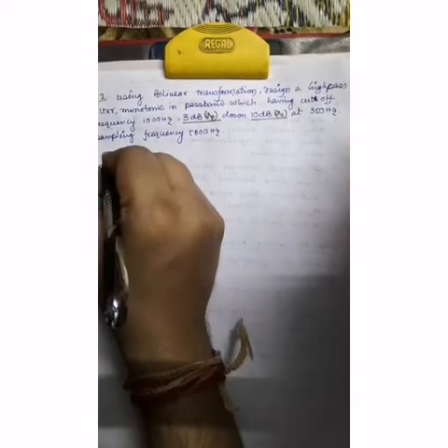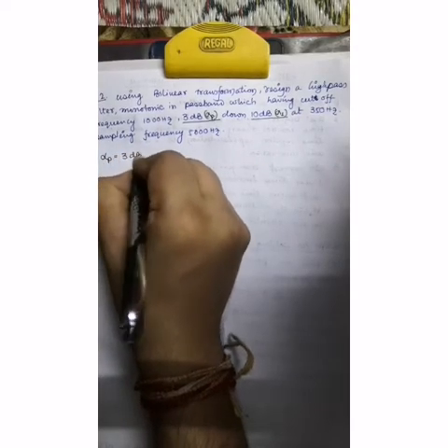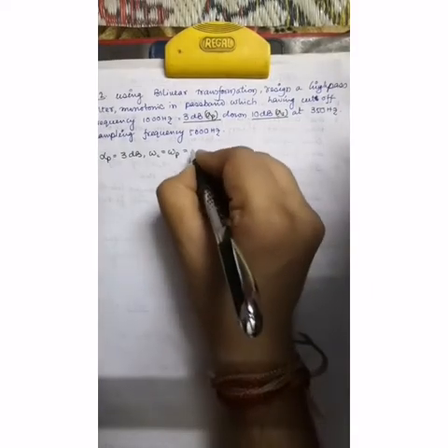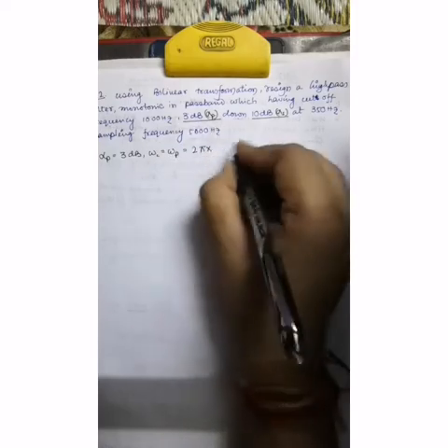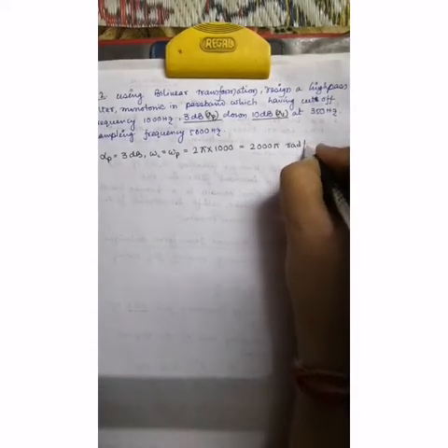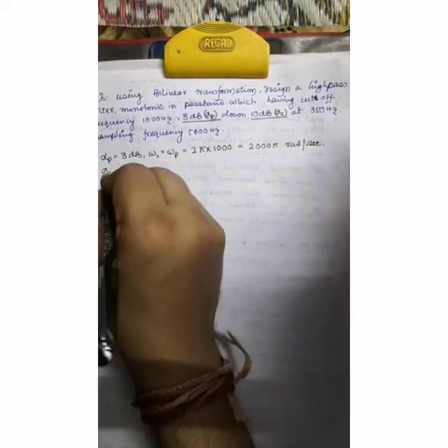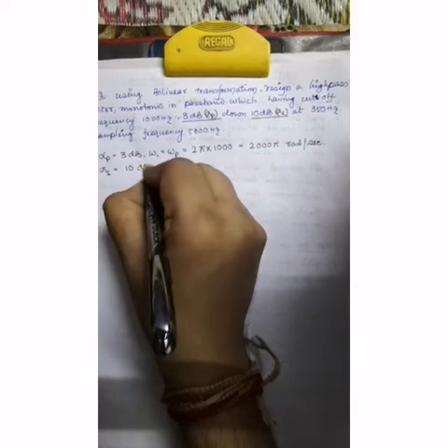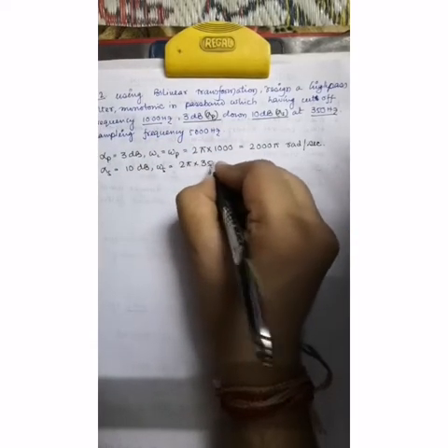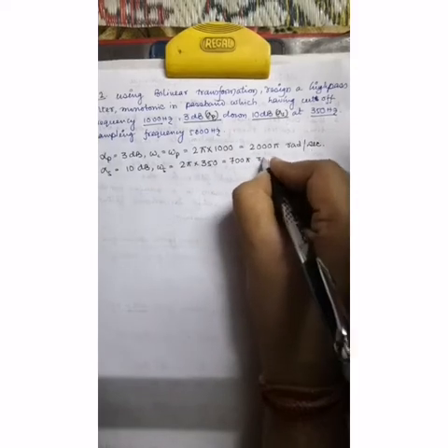So the first step is to find the pre-warping analog frequency. In the question the given part is alpha p, the value is 3 dB, and for a high pass filter omega c is equal to omega p. Omega means 2 pi f, so 2 pi and frequency value is 1000, it becomes 2000 pi radian per second. Next is alpha s, the value is given 10 dB, and omega is omega s, simple 2 pi f, that is 2 pi, frequency is 350, so 700 pi radian per second.